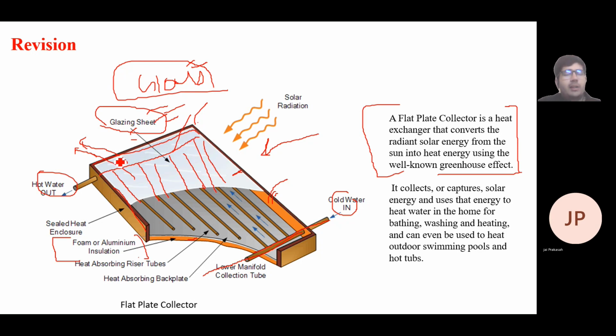So it will work like a greenhouse effect, and this will heat these tubes, and these tubes are good conductors because they are made from good conductive material. So they will conduct that heat to the fluid inside those tubes. The cold water is flowing through these tubes, so the cold water will be heated.